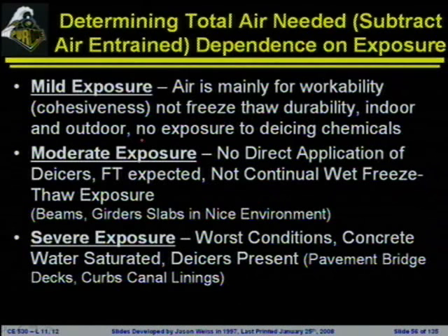Mild exposure can be used in indoor and outdoor concrete. Also, there'll be no exposure to de-icing chemicals. Moderate exposure, no direct application of de-icers, but they may be around. You may see something splashing up onto them. Freezing and thawing is expected, but it's a relatively nice freeze-thaw environment.